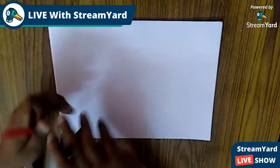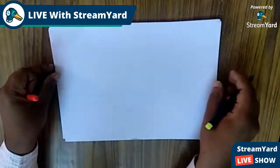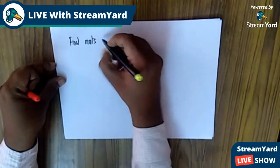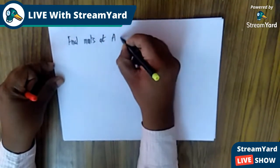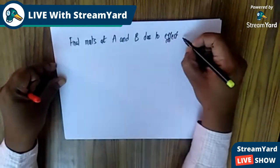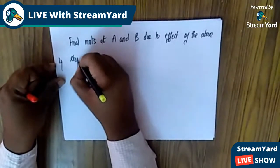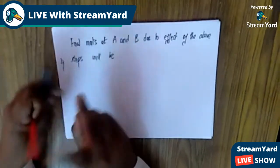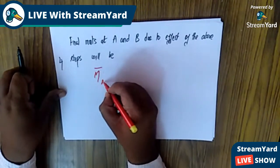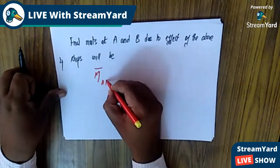Okay. Finally, we are now in a position to sum up all the quantities which we derived in step 1, step 2, step 3, and step 4, and come to the final slope deflection equation. So the final moments developed at the joints A and B due to the effect of the above 4 steps, I am denoting these final moments at end A as M bar AB.